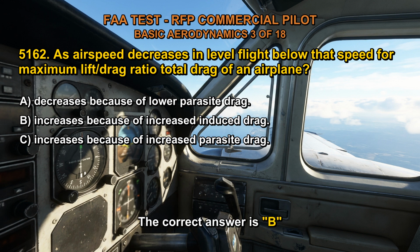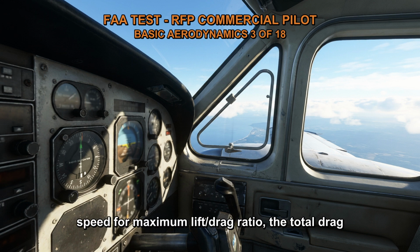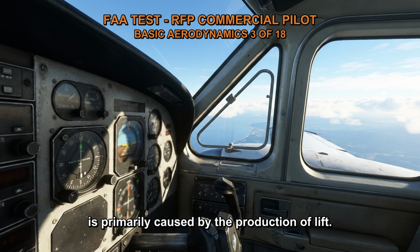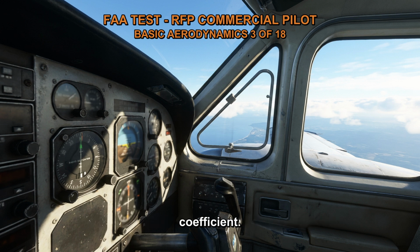The correct answer is B. As airspeed decreases in level flight below the speed for maximum lift/drag ratio, the total drag of an airplane increases because of increased induced drag. Induced drag is the component of drag that is primarily caused by the production of lift. It is inversely proportional to the square of the airspeed and directly proportional to the lift coefficient.